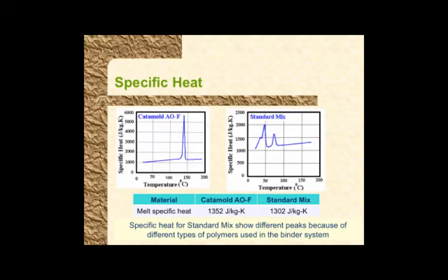Okay. Heat capacity, ability to store heat. The more powder you have, the less polymer you have. Polymer is what is going to store heat better. Polymers have a higher heat capacity than powders do, right? So solids have a lower heat capacity compared to liquids. There's less mobility of atoms in solids compared to liquids, and so the ability to store heat in different forms of energy is going to be lower.